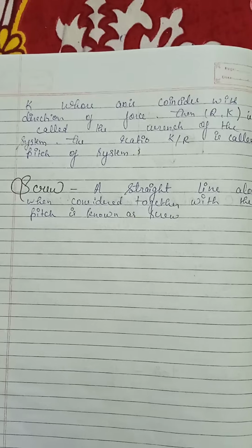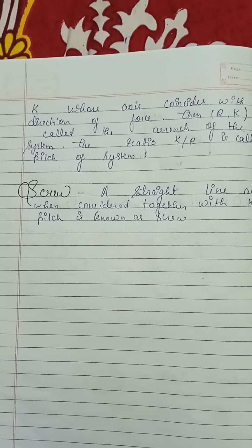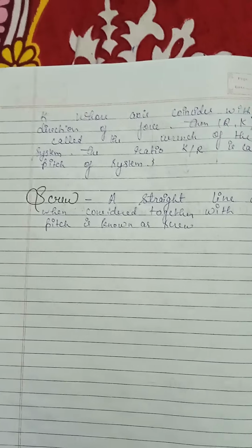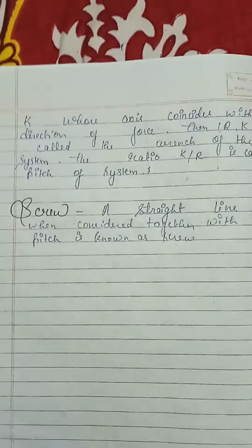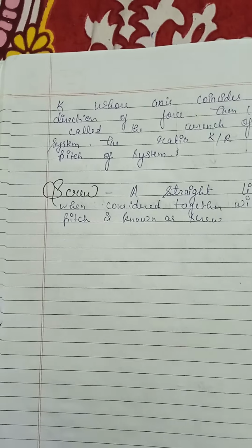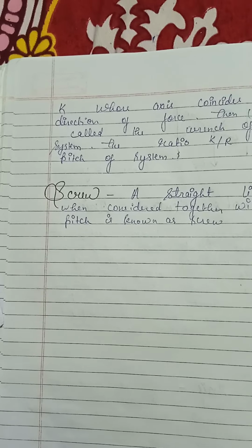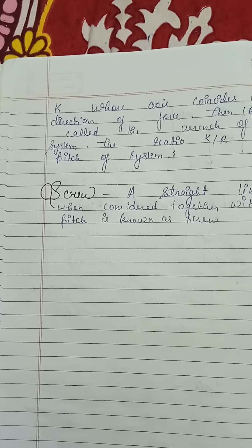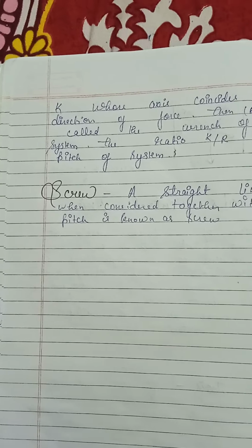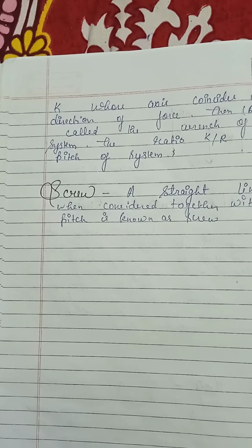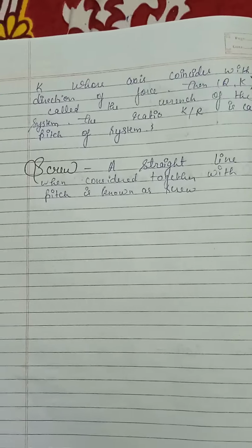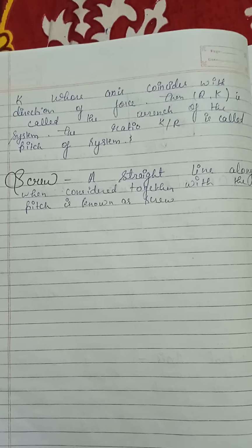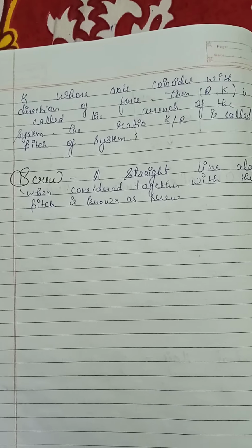For the pitch of the system, the p defined is known as the pitch of the wrench, and thus by taking the dot product of both sides of the equation G is equal to pR with R, we have R dot G is equal to p R dot R, or it can be written as p is equal to R dot G upon R square. Here R is X, Y and Z, and G is L, M and N, where the symbols have their usual meaning. Thus the conclusion is that p, the pitch, is equal to Lx plus My plus Nz upon X square plus Y square plus Z square.